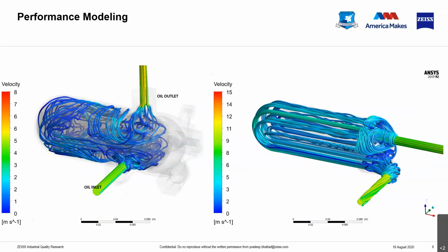One thing I wanted to point out is that if the part is not manufactured correctly, the pressure drop in different areas would be different. If the surface roughness is not accounted for very well, then you might have a very different, much greater area available for heat exchange if surfaces are fairly rough versus if the surfaces are fairly smooth. So once you start accounting for the amount of area available for heat exchange, most of the simulations get thrown out of the window because they're not practical anymore.